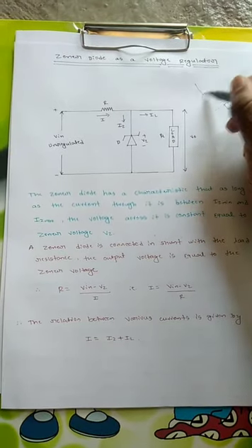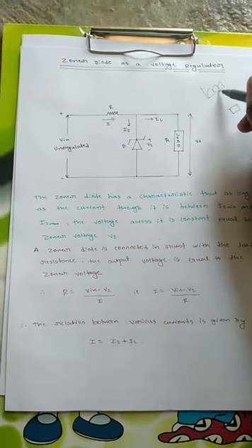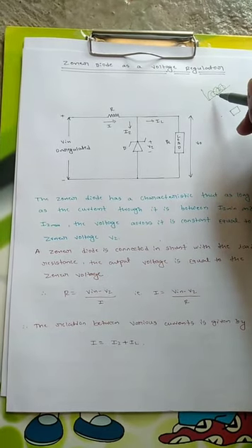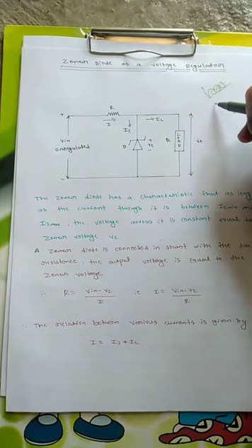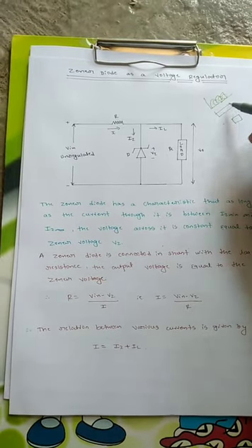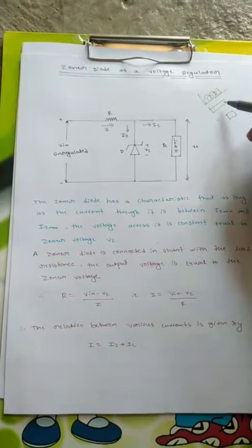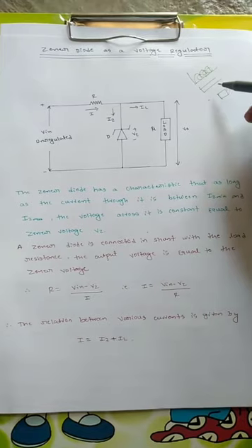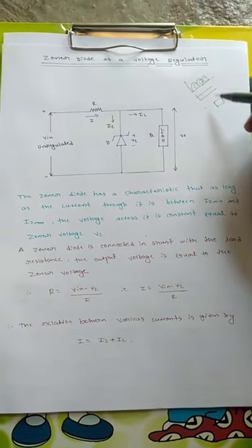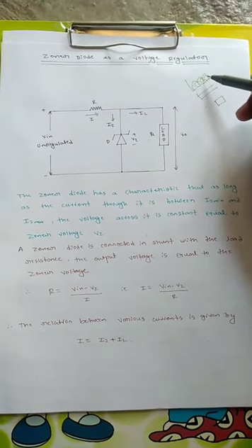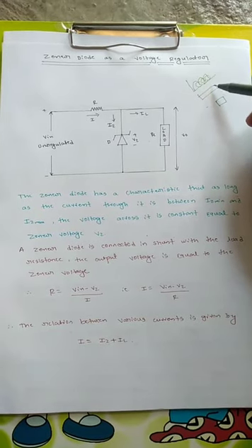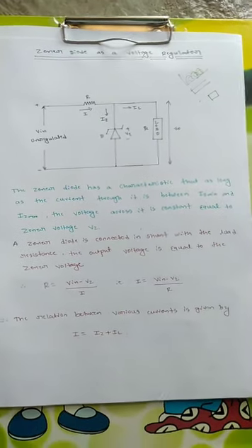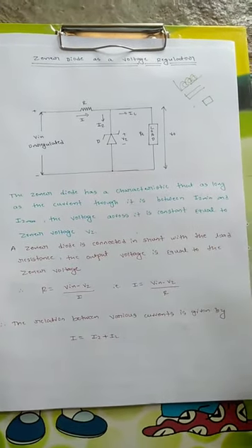When we rectify the voltage, it consists of peaks, right? These are the pulsating DC, which contains some part that returns to zero and again increases. But the smooth DC is a straight line parallel to the x-axis, so there are no fluctuations in the voltage. This type of voltage is needed for the working of DC components, so pulsating DC is not desired. Converting the pulsating DC into smooth DC is called voltage regulation, so we should have a constant voltage there.